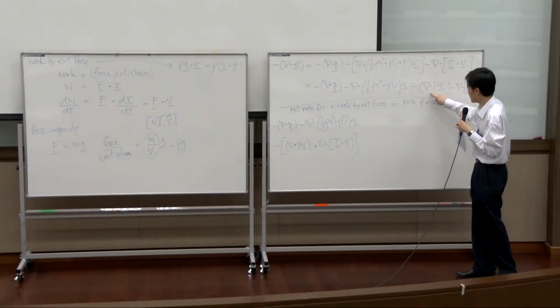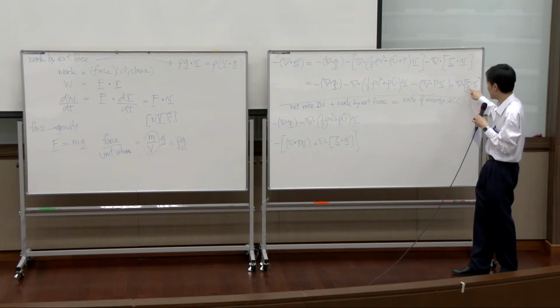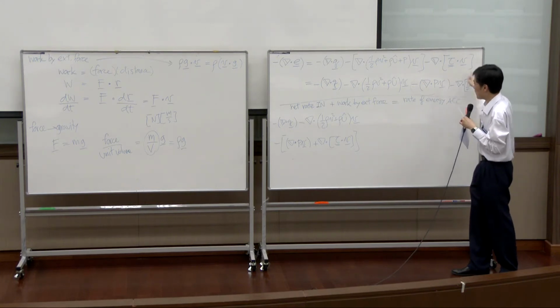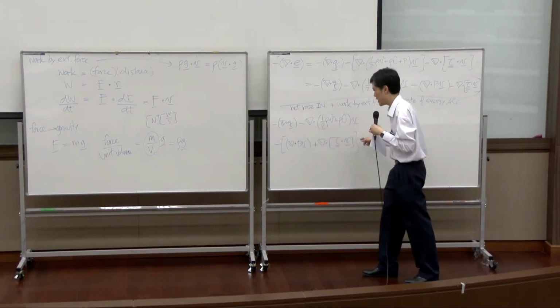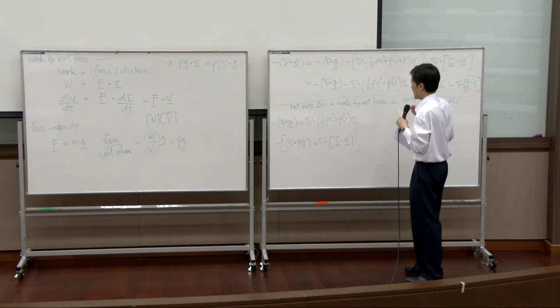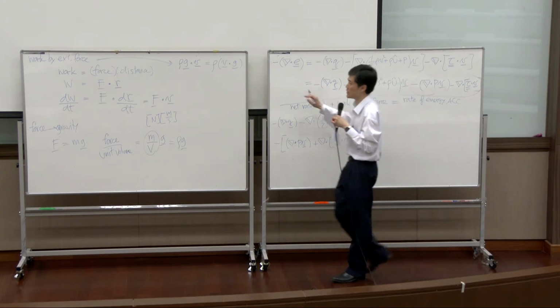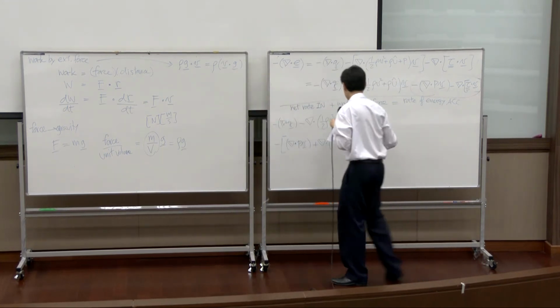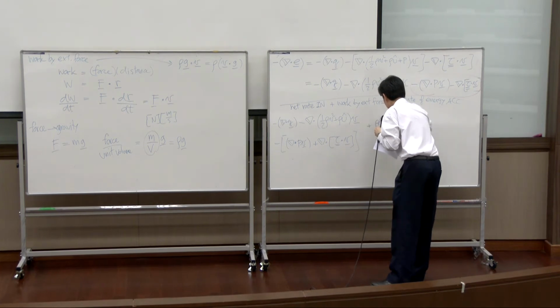This is flow work, and this is also molecular transport, work by molecular transport by shear stress. So they are some kind of the same thing, so I keep them together. You can say that these are basically flow work. And then work by external force, which is rho v dot g. So added by rho v dot g.